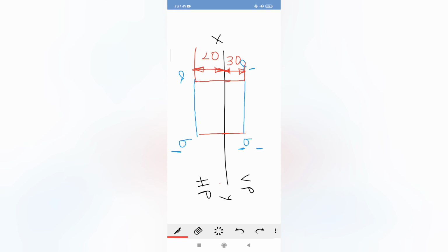Now, let us tilt the line making an angle of 40 degrees with VP. We know that vertical plane inclinations can be seen from which view? Top view. That means on which plane? Horizontal plane. That means on the horizontal plane we have represented the line as A and B1. The projection AB1 is to be tilted up to an angle of 40 degrees. For this, you have to take your compass with A